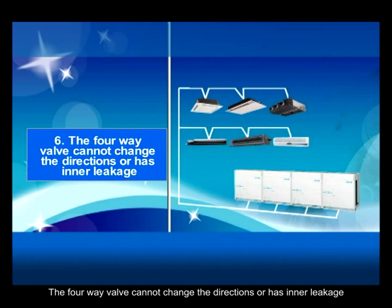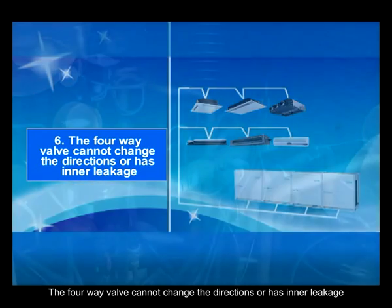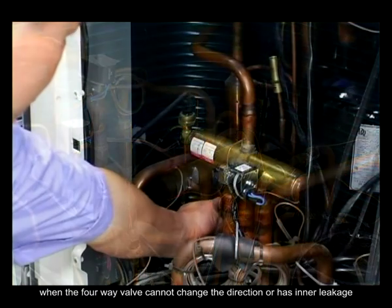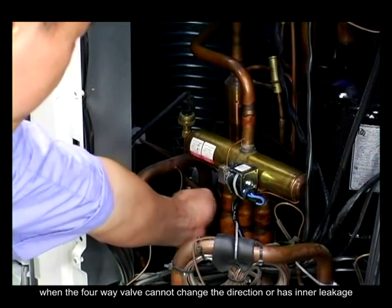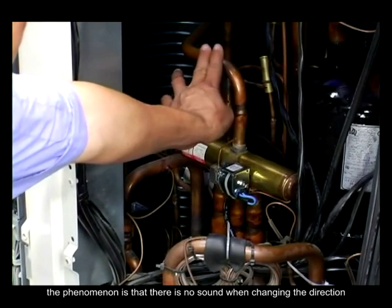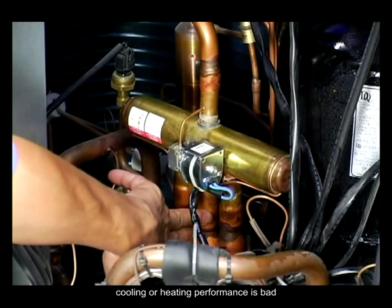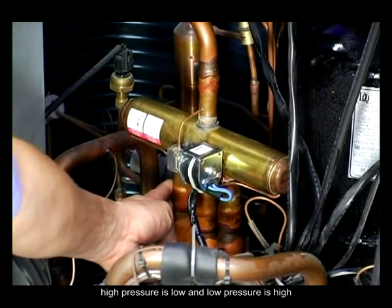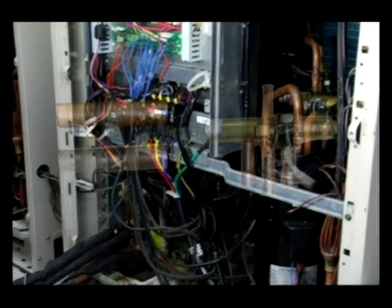The four-way valve cannot change directions or has inner leakage. The repairing methods of four-way valve malfunction. When the four-way valve cannot change the direction or has inner leakage, the phenomenon is that there is no sound when changing the direction. Cooling or heating performance is bad. The middle pipe on the downside of the valve has higher temperature. High pressure is low and low pressure is high.